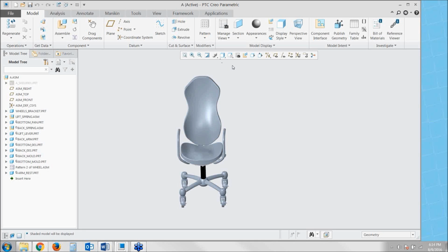In order to get into that, first off, we'll show some of the new differences with Creo 4. One of the first things before we get into the rendering piece fully is this scene background. Scene background and ambient occlusion are two commands that were hidden in Creo 3, I guess you would say. They were not as visible, so people didn't use them as much, and so they popped them out onto the in-graphics toolbar right here.